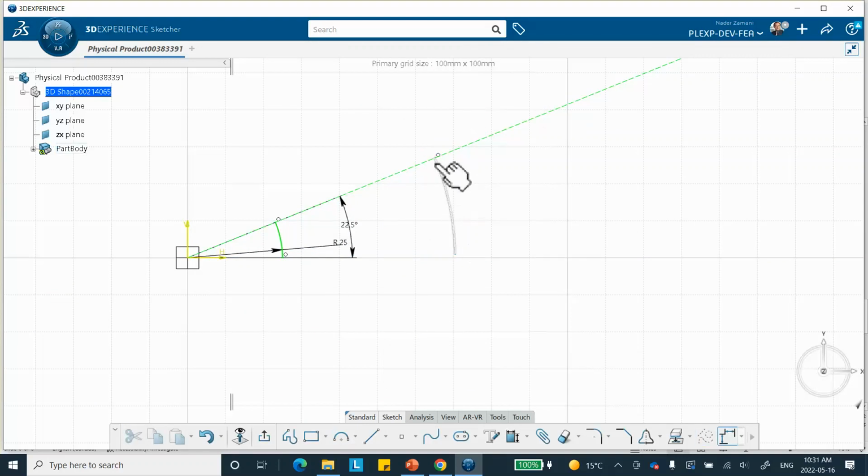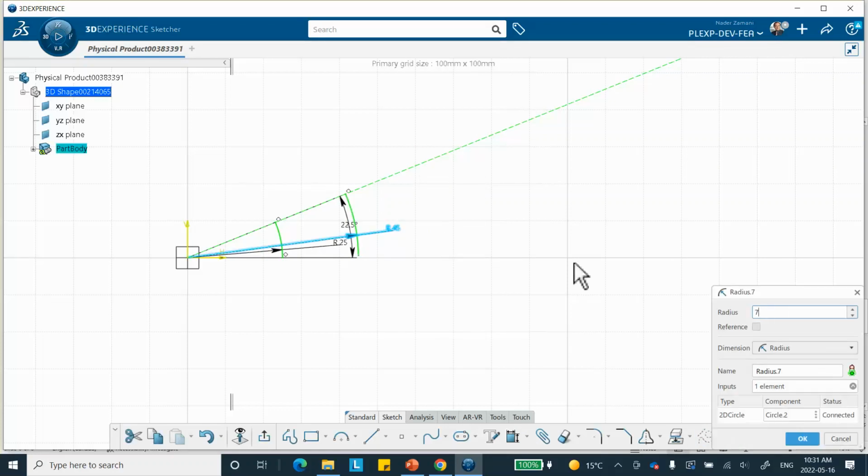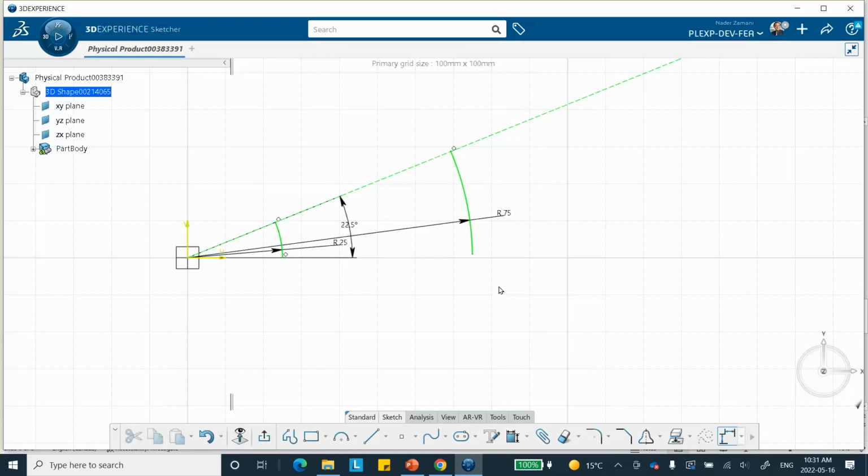I was careful to make it coincident as I was drawing this, so that's going to be 75 millimeter. Okay, so what you see there, oh, 75, not 45, 75. All right. The only thing is that this point is supposed to be coincident on that axis, so let me do that. Control that, and we make it coincident. Okay, pushed it down. Very good.